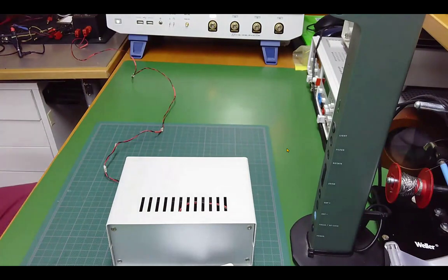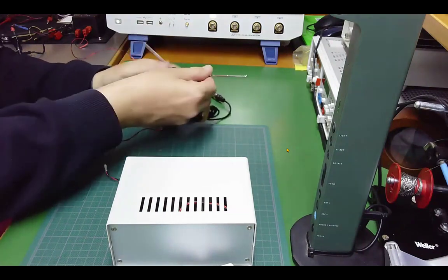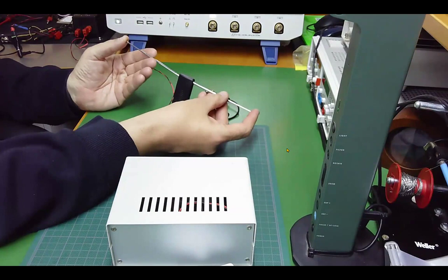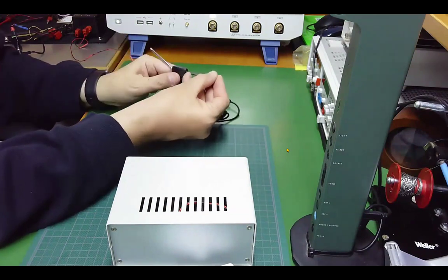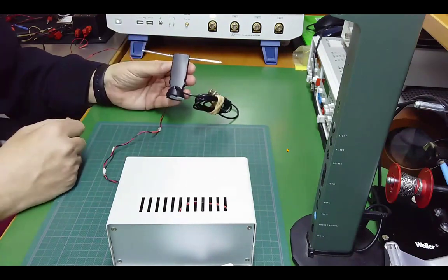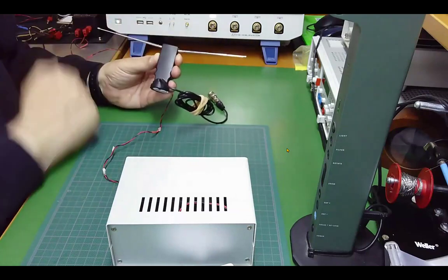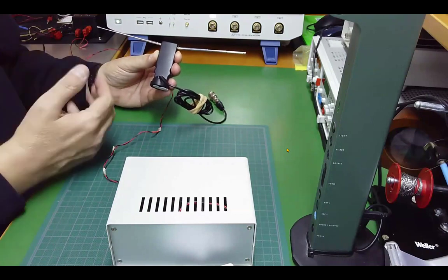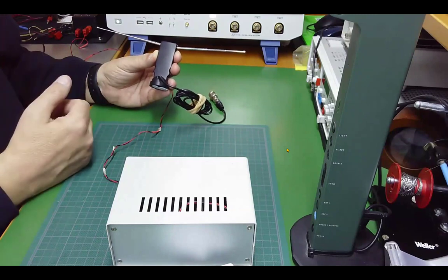For my demo, I will be using this antenna. It's a small antenna. You can see that I have rods, and obviously it's very short. It's very nice for traveling or for demos. If I reduce the length of the antenna, I am able to tune the antenna for higher frequencies. If you increase the length of the arms of the antenna, you will be able to measure lower frequencies. Obviously, to have a good antenna for very low frequencies, the size of the antenna will be very big.